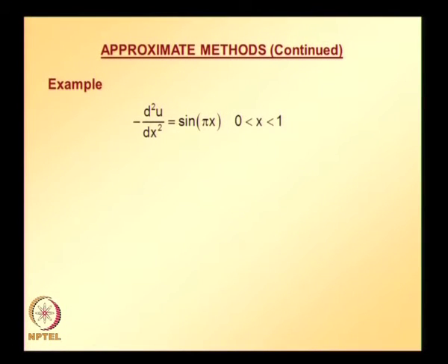So, now let us go back to the problem. These are the 4 steps which are common for any boundary value problem. Once we follow these 4 steps, we can get the equivalent variational functional. Once we get it, we can substitute an admissible trial solution into it and minimize the variation of that functional, or we need to apply the condition that the variation of that potential energy functional is equal to 0.